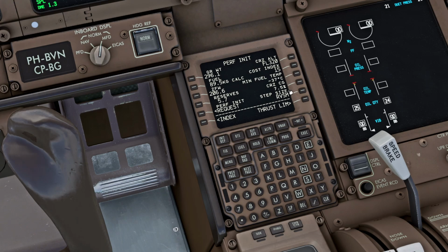So the flight plan will usually come with a value. You can also enter this in SimBrief, and throughout the flight, if you notice that you have been flying with a cost index of 200, for example, but in the air you notice you're actually arriving quite on time, especially on long hauls, then you can select a lower cost index to save a little bit of fuel at the expense of maybe arriving a few minutes later, but then at least you are still on time and you're saving a little bit of fuel. So it's important to play around with this value in cruise time.